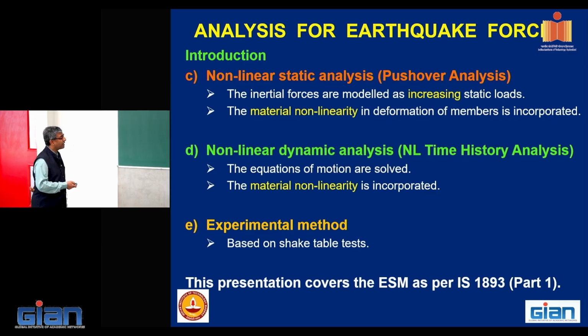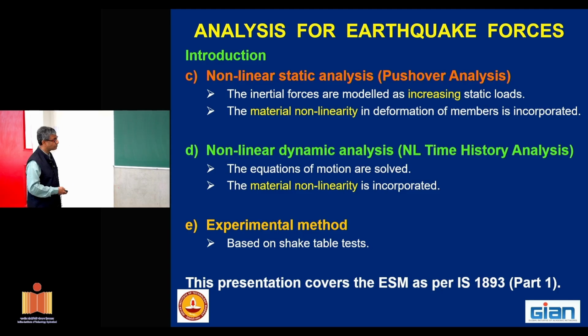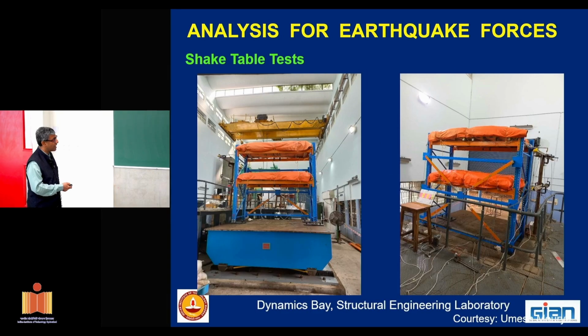The nonlinear dynamic analysis, which is related to the time-wise variation, is more within academic circles. And we can also have an experimental method which is based on shake table tests. Now here I am just covering the equivalent static method as per IS 1893. Now this is a shake table we have in our lab. I am just showing a picture from our lab; our steel students mostly use this shake table. Also our masonry students, depending on the payload. Payload means the load that it can carry. We cannot do concrete specimens here, but rack structures or masonry structures can be done on this type of shake table.